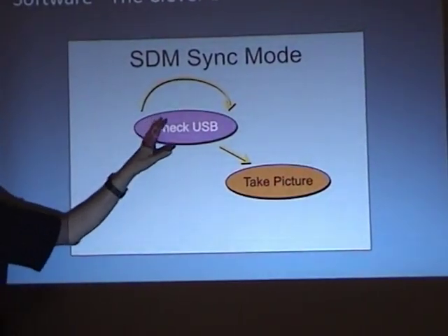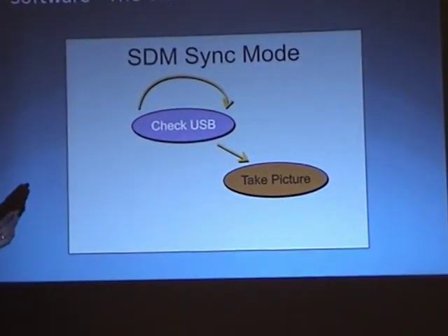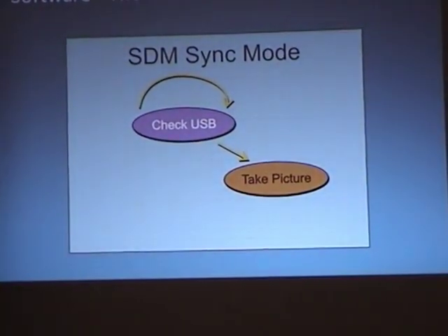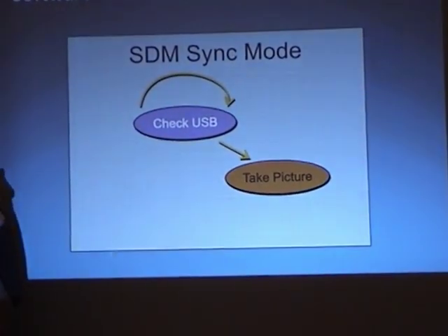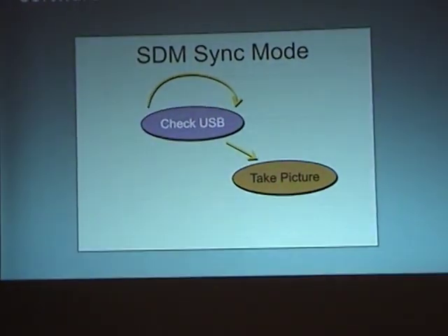When it sees that signal go away, it goes over here to the take picture routine. So instead of going off doing a dozen different things and you have no idea where it's at, we know exactly what both cameras are doing when you release the button. That's why it takes pictures on the release of the button. Jumps into this take picture routine. My little rig that I'm using, I've tested it. I get 1/5000th of a second sync on it very, very reliably, which is amazing. Flash, not so good. Other people claim a 20,000th of a second. I honestly don't believe it, though I've seen some of the numbers.